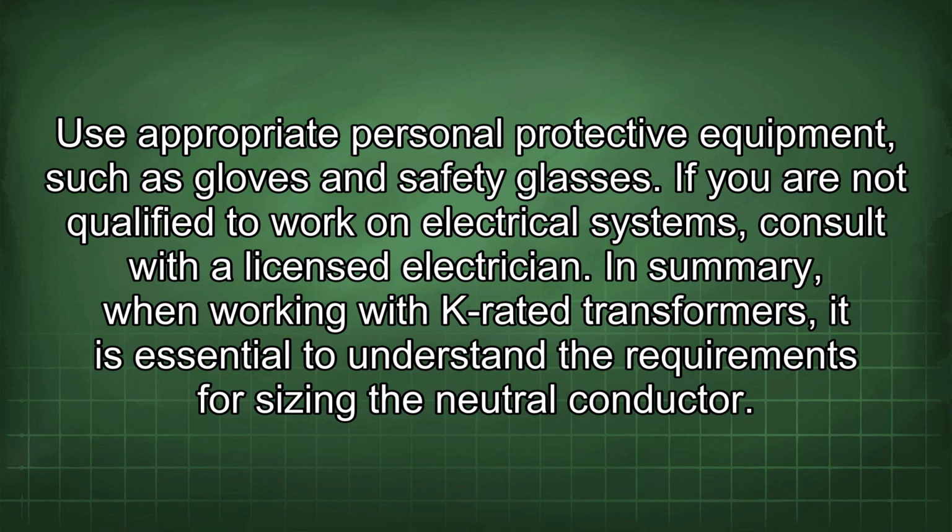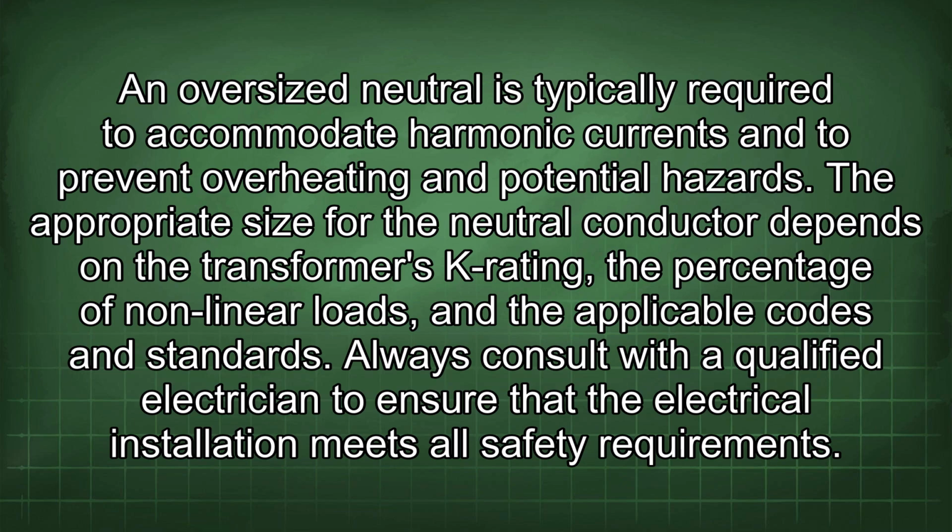In summary, when working with K-rated transformers, it is essential to understand the requirements for sizing the neutral conductor. An oversized neutral is typically required to accommodate harmonic currents and to prevent overheating and potential hazards. The appropriate size for the neutral conductor depends on the transformer's K rating, the percentage of nonlinear loads, and the applicable codes and standards. Always consult with a qualified electrician to ensure that the electrical installation meets all safety requirements.